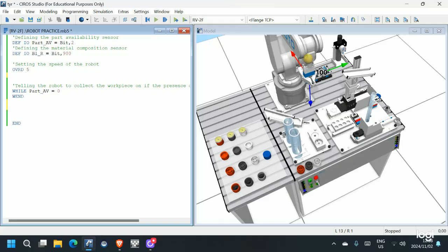They're saying the gripper opens, so we'll add a comment saying opening the gripper. We'll use open one, so we open the gripper. And after opening the gripper, before the robot moves, we'll delay for 2 seconds. So just DLY for 2 seconds.